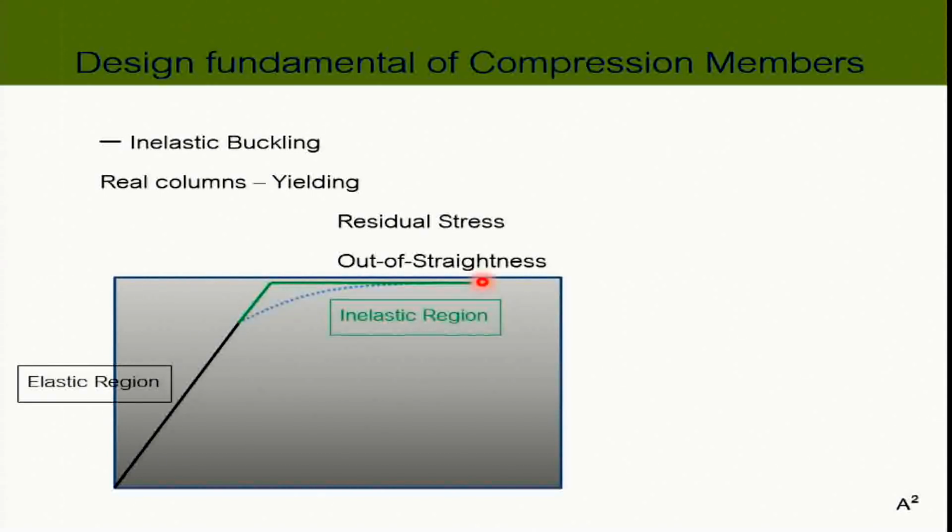With one tiny, crooked shape somewhere, it means that when you apply the axial force, it's going to cause more internal force in the structure because of the eccentricity, right? Because the force does not go straight to the centroid because the column is crooked. So we call that out of straightness, because your column cannot be perfectly straight all the time. So three things we need to take into account and readjust Euler's buckling curve.